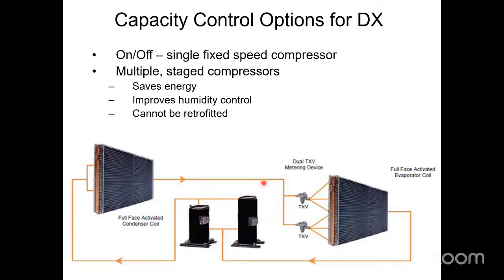I could have a single on-off fixed speed compressor, just like you have probably at your house. The compressor turns on, the compressor turns off, and I turn it on or off more to get more or less cooling. I will get the desired effect. I will get the amount of BTUs of cooling that I want, but I'm gonna have to run it 10 minutes and then leave it off for 3 and then on for 9 and then on for 4 and whatever.